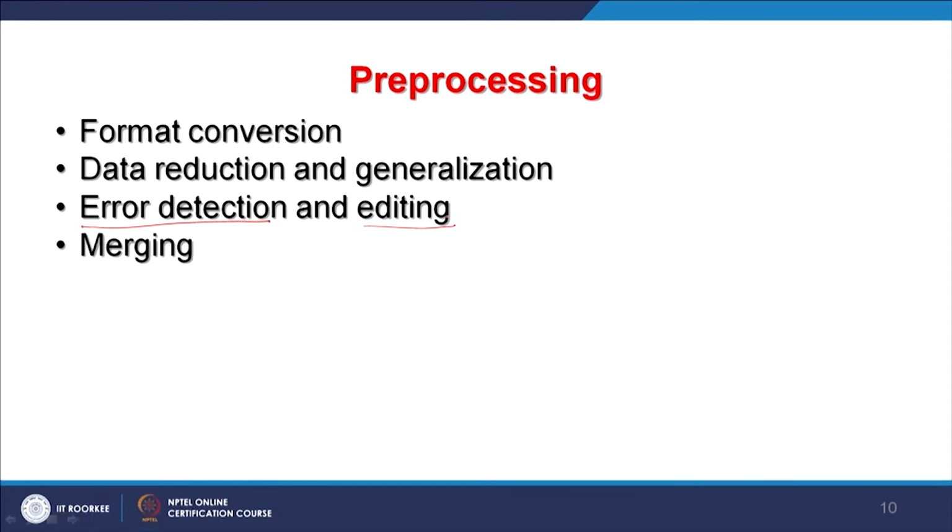Merging means if I am having two maps side by side, like two topo sheets having adjacent numbers, then I want to join them, that is also called merging, but in raster data merging has got different meaning. So, we will be discussing this also in detail. And then edge matching, if you are having two adjacent topo sheets data, then sometimes because of projection issues, the data on the boundary may not match very perfectly automatically. So, sometimes manual edge matching is also required.